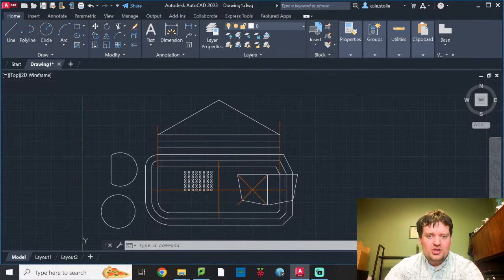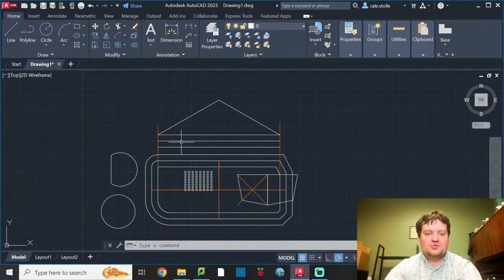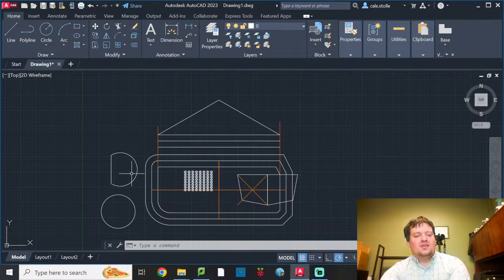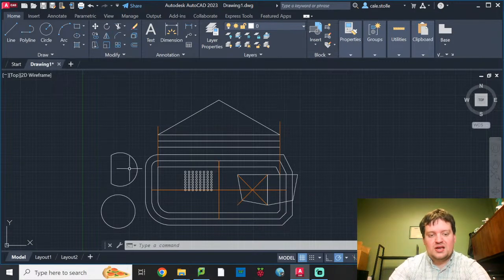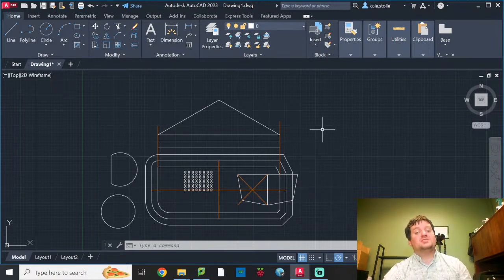Here you need to come up with your triangle up at the top. It has to be trimmed. The way that I design this is that it's directly over the center line. You will need to have this triangle shape up here. You're going to need to have these two circles, which were copies of our original circle. This circle is going to need to be trimmed with this straight line on the side, and then you will need to have an array of small circles right here. So those are all of the objects that I'm expecting you to have as part of this assignment.